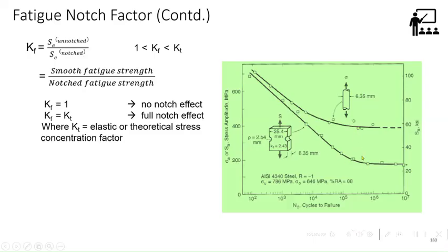Same material, same fatigue level, you see how they are getting very widely different at the higher cycles, at 10 to the power 4 onwards. Here there is nothing much. Below 10 to the power 3 is low cycle fatigue, you don't worry. But it starts to differ remarkably from 10 to the power 4 onwards. So you get this.